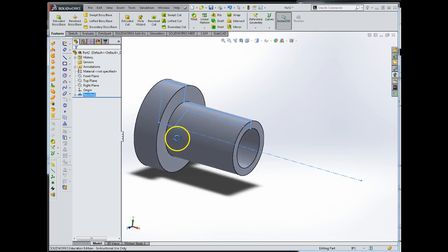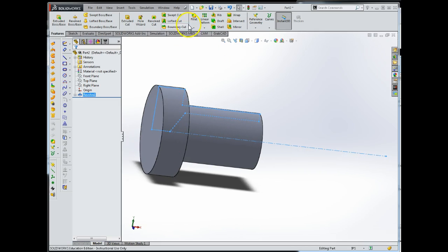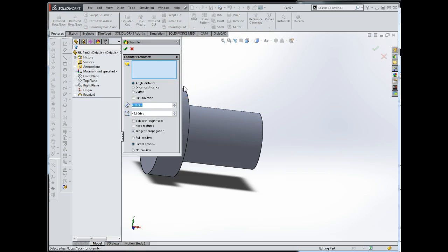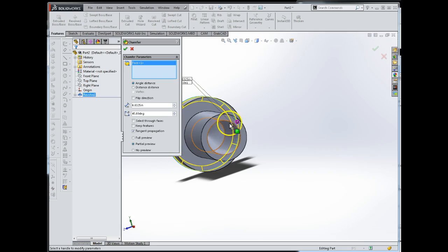Okay, notice that our feature is hollow as our sketch was indicated. We can see our sketch highlighted in blue. Adding some chamfers to this next. Again, the chamfer command is hidden underneath the fillet command. We're looking for some values of 0.0325. I'm going to keep the default of 45 degrees, and we're going to select this surface here, or this line here rather, and on the back side we're creating a chamfer allowing something to slide in.